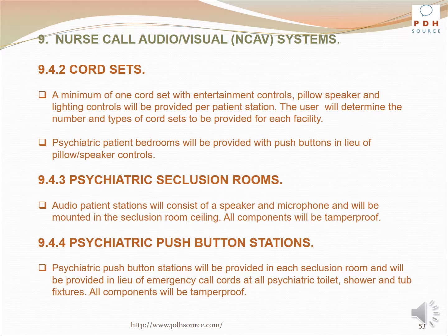Psychiatric patient bedrooms will be provided with push buttons in lieu of pillow speaker controls. Audio patient stations will consist of a speaker and microphone and will be mounted in the seclusion room ceiling. All components will be tamper-proof. Psychiatric push-button stations will be provided in each psychiatric seclusion room and will be provided in lieu of emergency call cords at all psychiatric toilet, shower, and tub fixtures. All components will be tamper-proof.